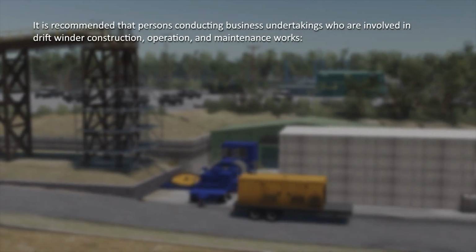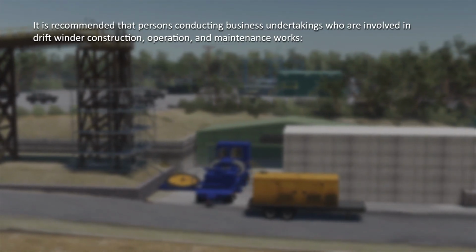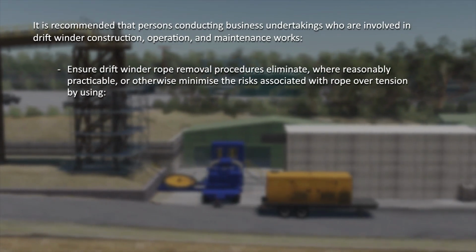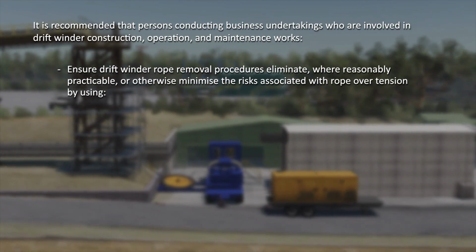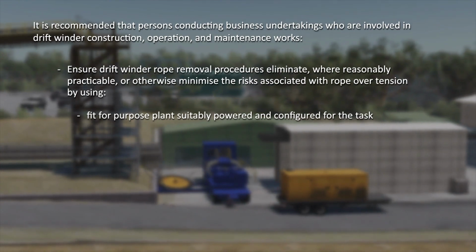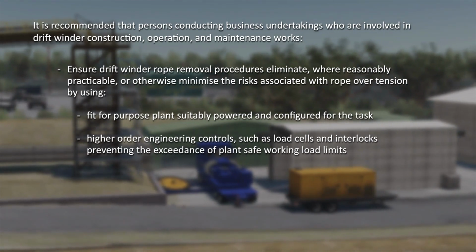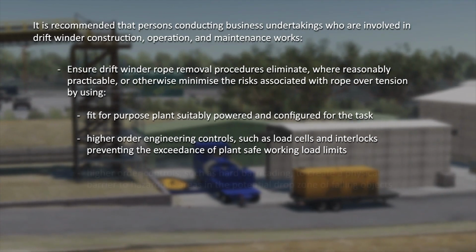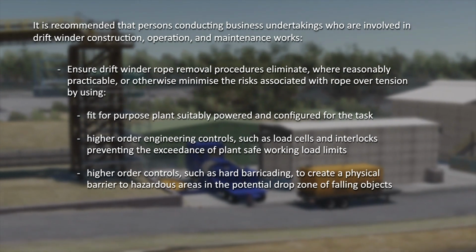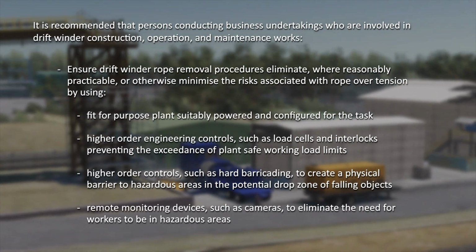It is recommended that persons conducting business undertakings who are involved in drift winder construction, operation, and maintenance works ensure drift winder rope removal procedures eliminate, where reasonably practicable, or otherwise minimize the risks associated with rope over-tension by using fit-for-purpose plant suitably powered and configured for the task, higher-order engineering controls such as load cells and interlocks preventing the exceedance of plant safe working load limits, higher-order controls such as hard barricading to create a physical barrier to hazardous areas in the potential drop zone of falling objects, and remote monitoring devices such as cameras to eliminate the need for workers to be in hazardous areas.